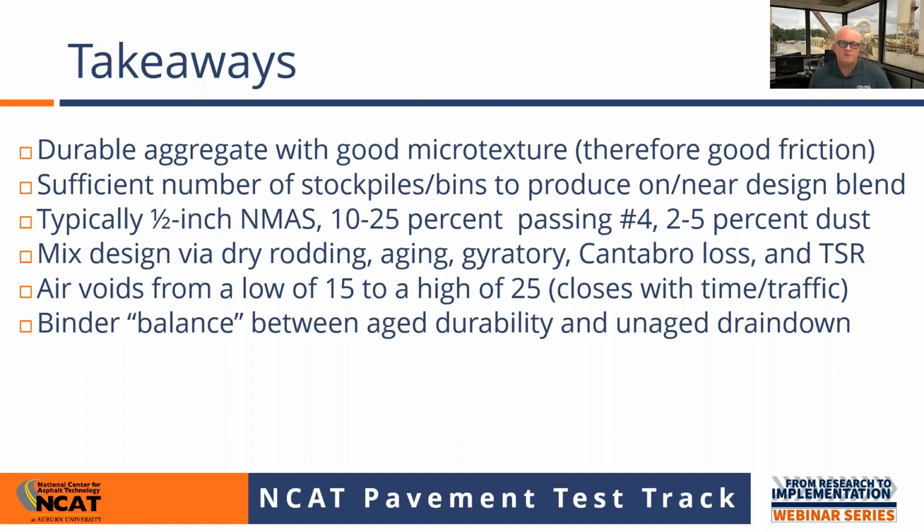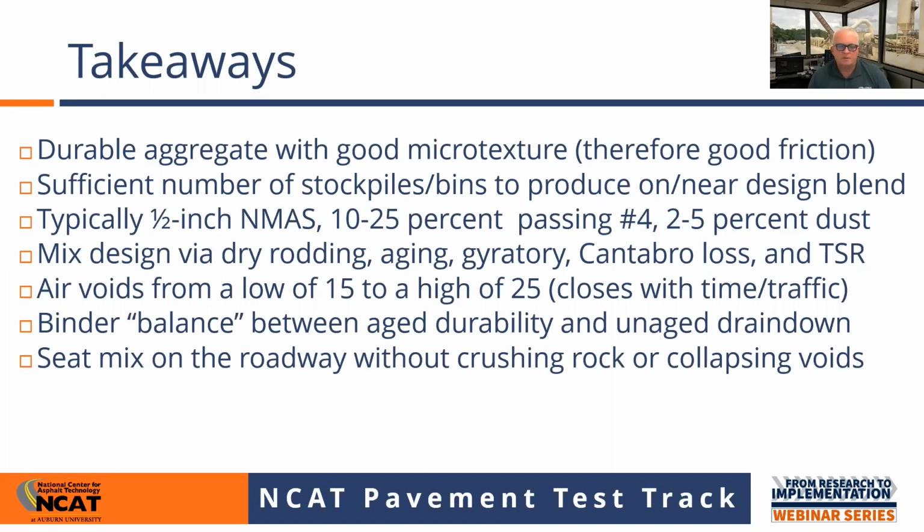We talk about balanced mix design for dense grade mixes, but I think this is a type of balanced mix design, because you really want to balance long-term durability with short-term drain down, and then the flushing and the bleeding problems that you can have as well. So the optimum binder content is in that range. So really, I consider this a type of balanced mix design.